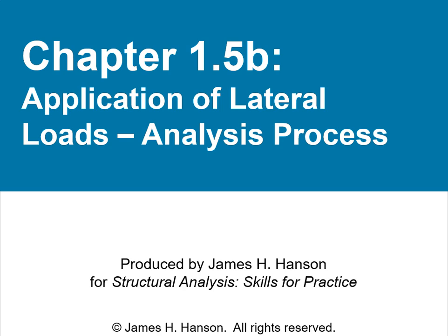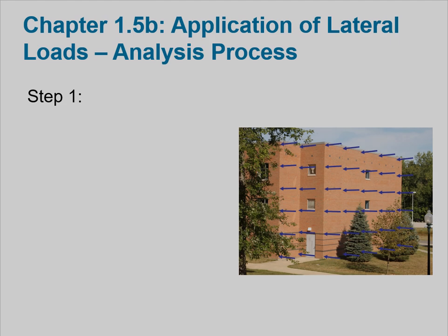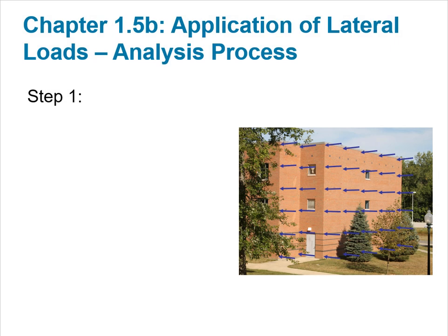The first video for this section was an overview of how lateral load becomes point loads acting on lateral load resisting elements. Now let's talk about a process we can use to perform that analysis. There are 5 steps we follow to go from lateral load on a structure to point forces on the lateral load resisting elements. The first step is to calculate the total lateral load applied to the structure.